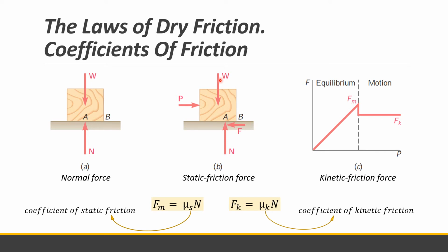They are also somewhat dependent on the current or exact condition of the surface. So it depends on the surface, whether it is flat or somewhat curved or crooked. But in terms of the values of the coefficients of friction, there are given values depending on the material, for example metal on metal, metal on wood, or metal on stone. So our coefficients of friction are available.